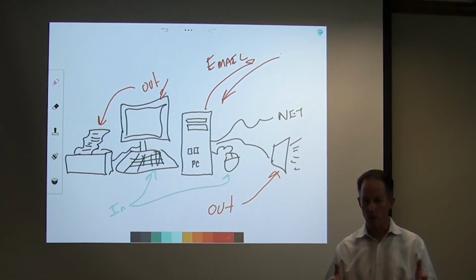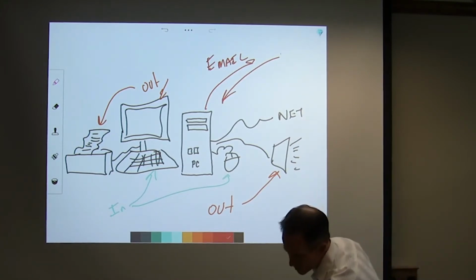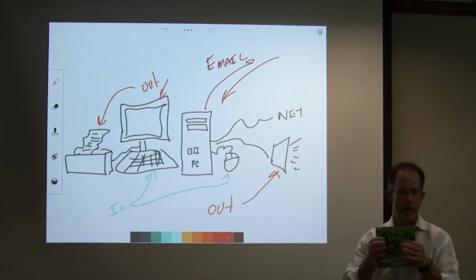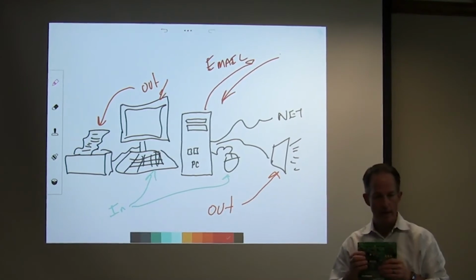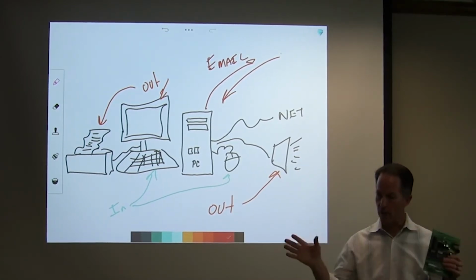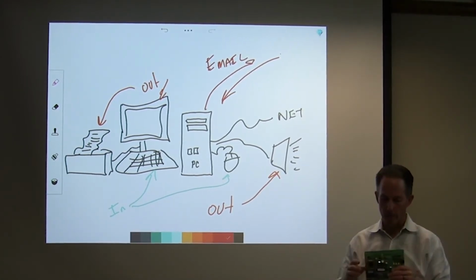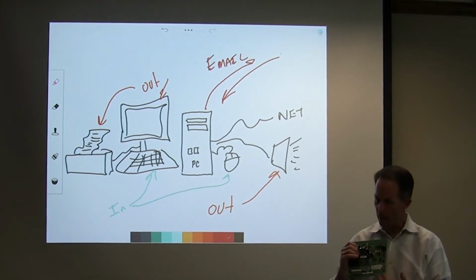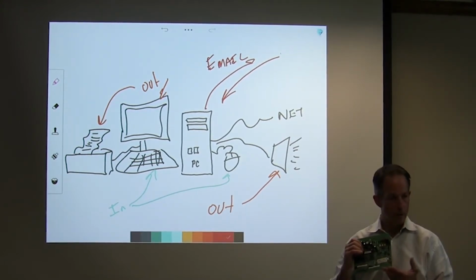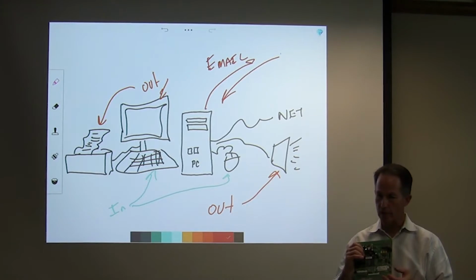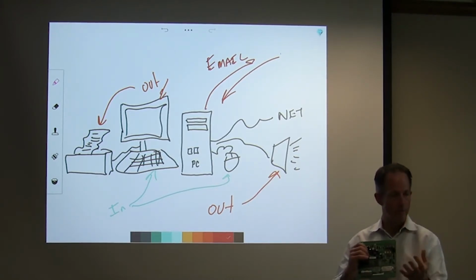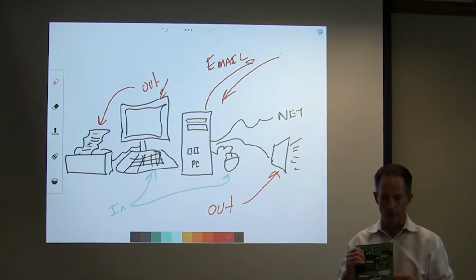and it's very slow. I believe it's 1200 baud. So it's a very slow proprietary kind of thing. But it's the easiest to troubleshoot. If I have one of these cards and for some reason I have a number of them not talking, I can put my meter down on the connections for the communication, and I will see either 5 volts or 0 volts or a fluttering between the two.